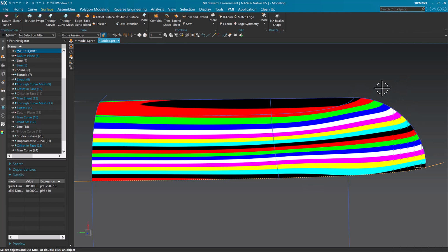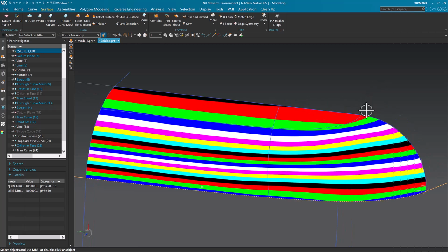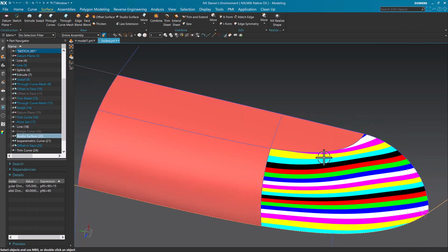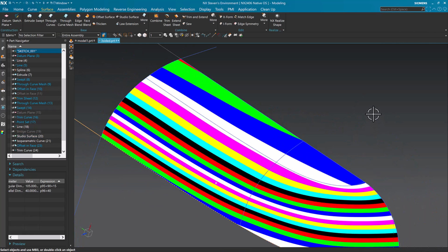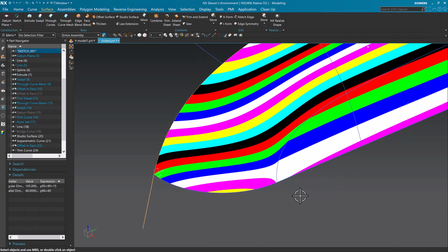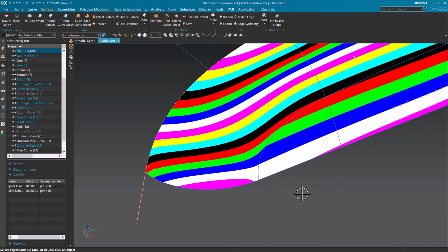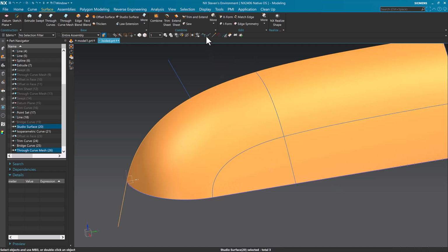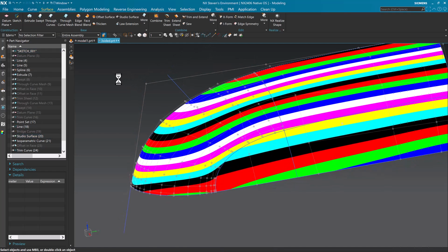And that way I could potentially end up with G2 or something that looks like G2 because I fudged it in using 2 conics, or put in a spline that is actually G2 across that boundary. So that way when I make this surface and it flows into it, this does go G2. Okay, but that is the constraint that we have, and that's just what we have to work with. But that is another way to build your 3-sided surfaces. And this is, in general, probably I would say the best way, because overall it's going to build the least complex of them all.